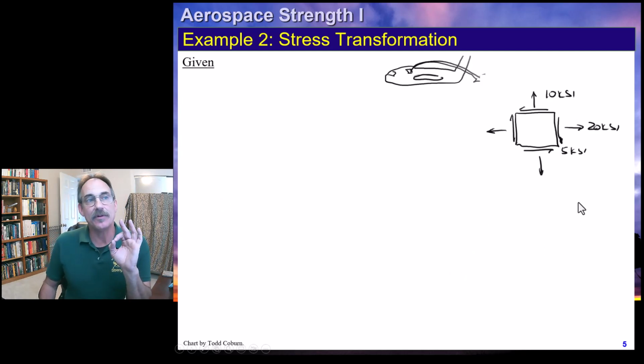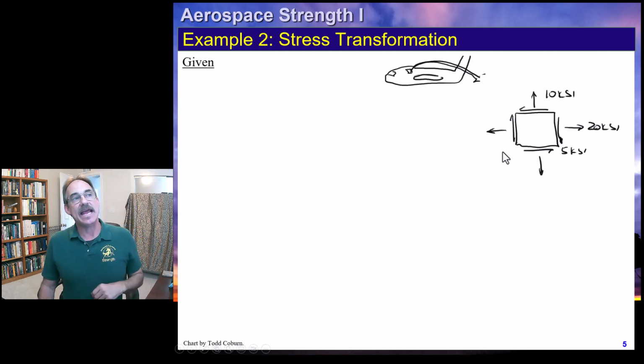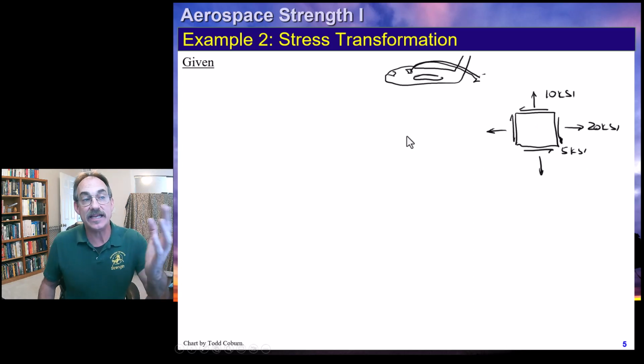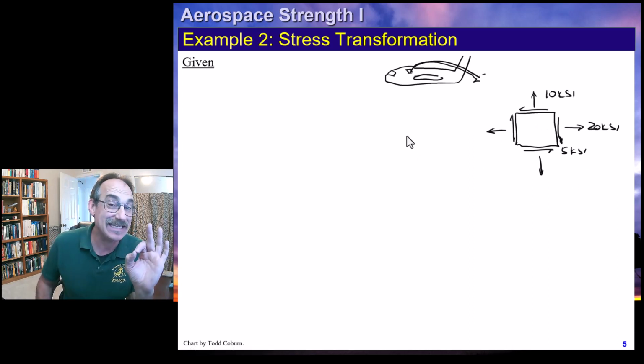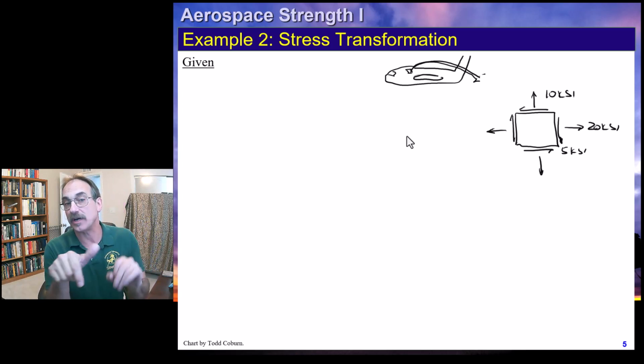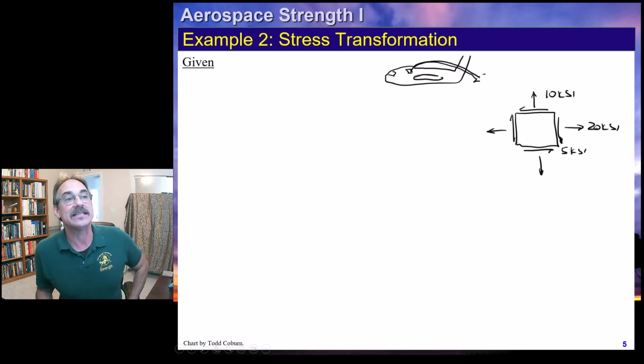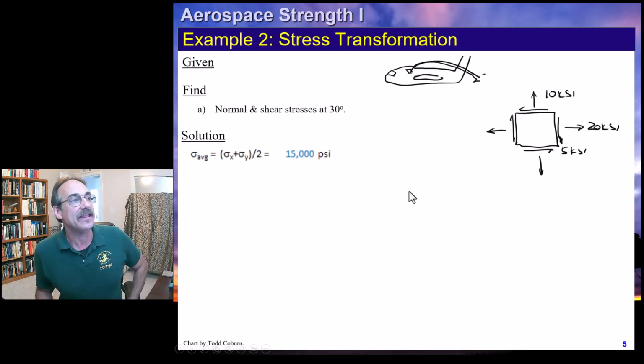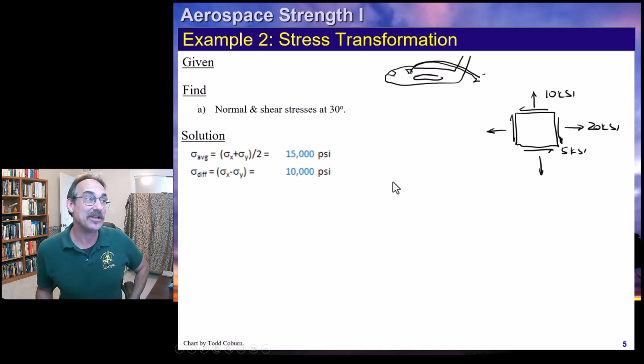If we take another example, let's say that we pull out an element and we get these stresses. You'll notice these stresses are identical to the last one, but in this case, on the rightmost face, our shear stress is acting down. That is defined as a negative shear stress, and therefore we plug in a negative value for that stress.